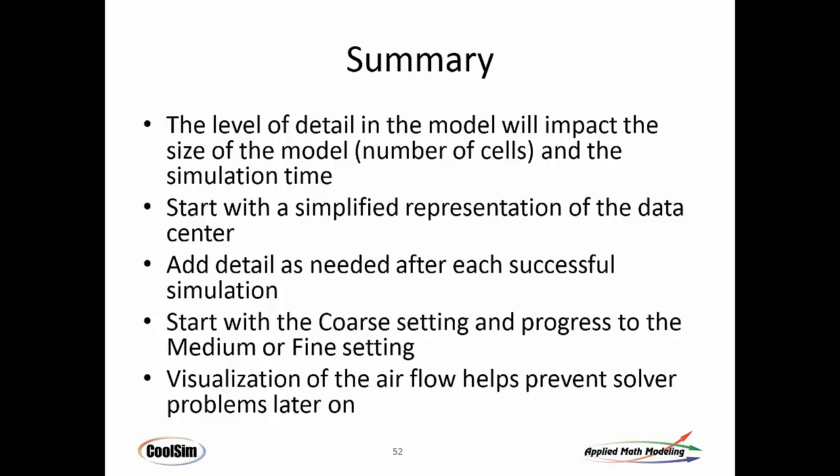A coarse degree of granularity will still give you a lot of feel for what's going on. It's going to show you the flow patterns. It's going to show you where the general hotspots are. You may need to dial it in later, but at least it will give you a good overview. I always start with a coarse mesh setting. That's generally good enough. I don't use medium or fine unless there's some tricky geometry in the room or unusual pressure conditions in the room. So it's defaulted to coarse. That's generally good enough. And then what I always do is look at my output.